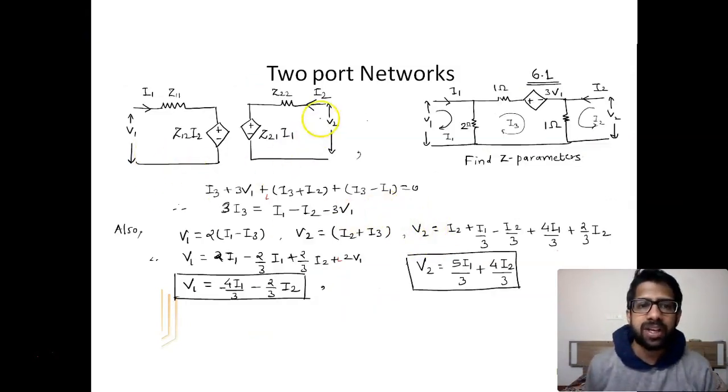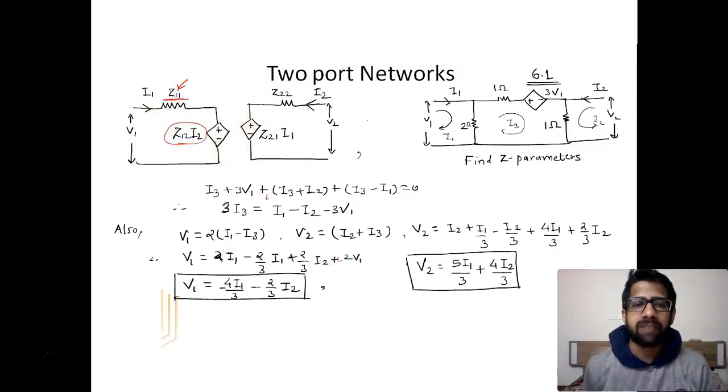So this is how you can represent a two-port network impedance parameter, wherein Z11 is nothing but an impedance value. Then you have Z12 into I2 giving the dimension of a voltage source which is dependent upon the current I2. That is why we have a diamond here. This is the dependent voltage source. Similarly for Z21 into I1 we have a dependent voltage source. V1 is made up of I1 into Z11 plus Z12 into I2.